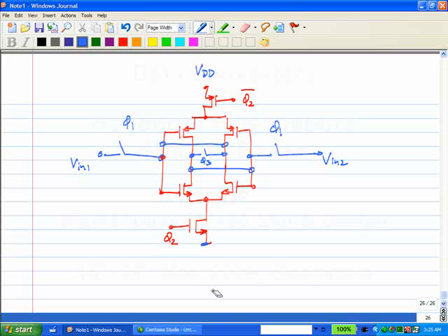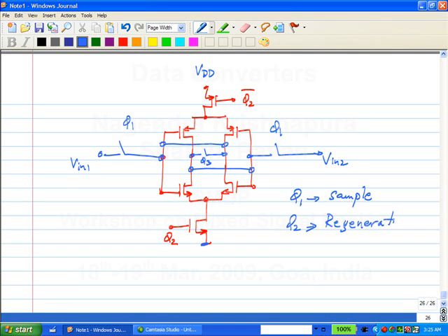Phi 2 is the phase where the rich becomes richer and the poor becomes poorer, right? So this is called the regenerative phase. And phi 3 is where past memory is cancelled, or rather zapped. That is called the reset phase.